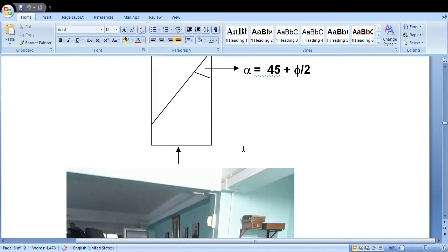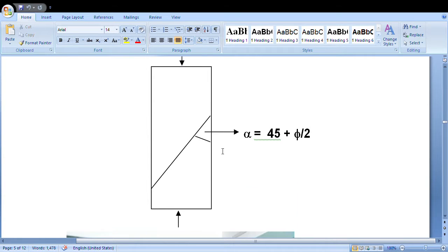I had already said that the surface of this test specimen, both top and bottom, should be so smooth, there shall not be any difference. A fraction of a millimeter may lead to serious results. So we should be very careful in preparation of the test specimen. If the test specimen is not correct, the entire process will be misleading for us.